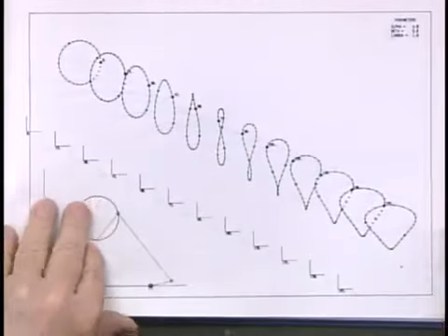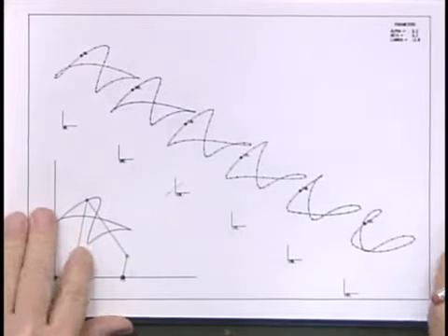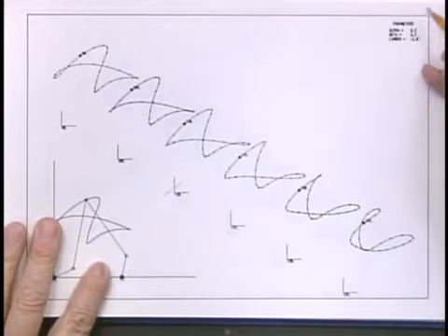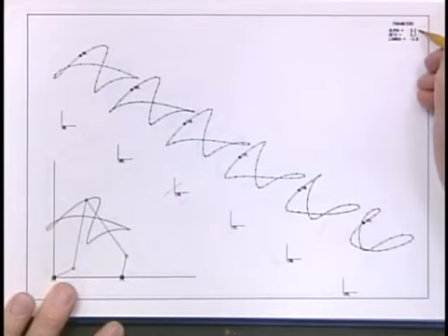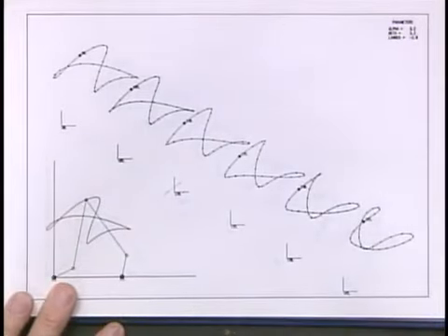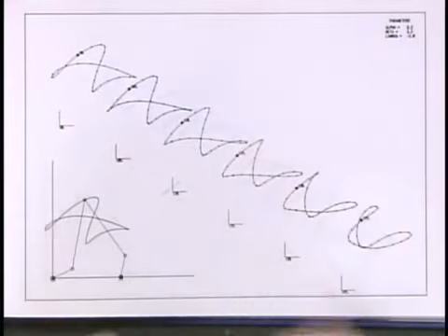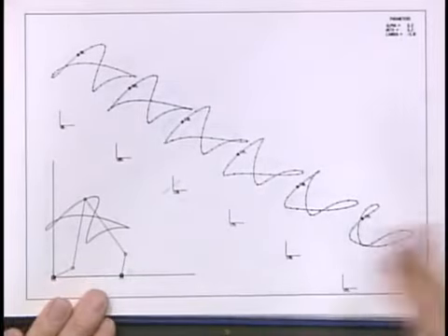So let's keep going. I want to get to some more interesting gear ratios. We're still in the ones. Here we come to a -2. Now this is starting to look a little more interesting. I won't bother to zoom in on it, but this says I have an alpha of 3.2, a beta of 3.2, and a lambda of -2. So the gear ratio here is -2, which means one gear is twice as large as the other, and there are only 2 of them, so they turn in opposite directions, and thus the negative sign.